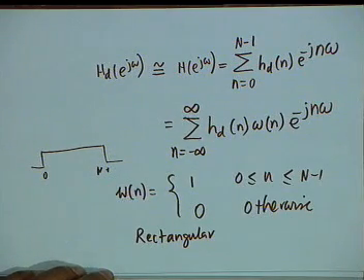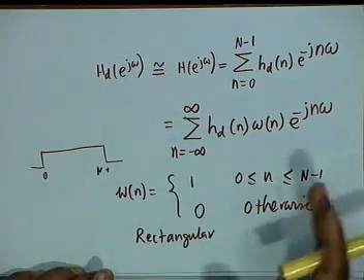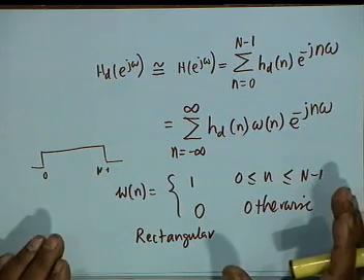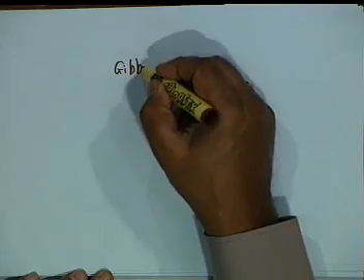In other words, you expand in Fourier series and then truncate it at some point, starting from n equal to 0, which looks like the total impulse response passing through a window. This window in this particular case is rectangular in shape. Now, rectangular windows have a number of disadvantages, and one of them is the so called Gibbs phenomenon.